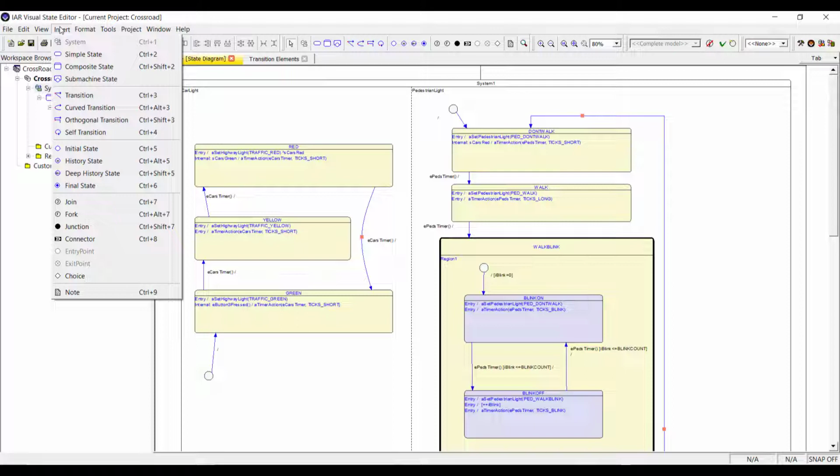So you can set up the logic. And the way it works is that you will be able to use low-code development here, because you graphically create your state machine, and then the idea is to integrate this generated code with some low-level drivers that might already be generated by the various silicon vendor tools, like HAL or BSP drivers and so on. And then you just build it and have your system running pretty quickly.